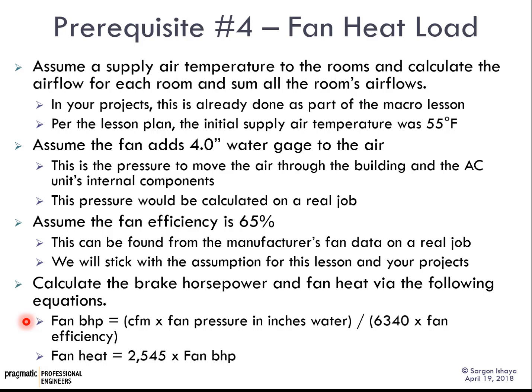Just because a fan has a 10 horsepower motor, it does not mean that it's using full power. It could be using 8 horsepower. Typically it's using less. So we learned in the fan selection lecture, where we were learning about types of fans, that the brake horsepower is different than the overall horsepower of the fan. So the fan heat is a function of the brake horsepower. It's not the overall horsepower of the fan. Make a note of that.